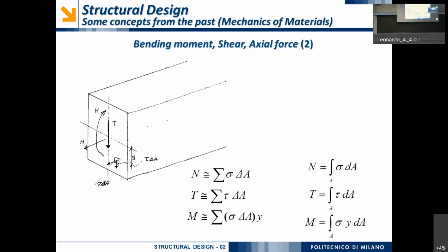I suppose that this is a bearing column in this row. Of course, I can observe that the axis is linear, but if I have to look to the cross section, this dimension is maybe larger than 1 meter. So we have to consider the real dimension of a cross section, okay? And so the internal forces T and M are resultants.